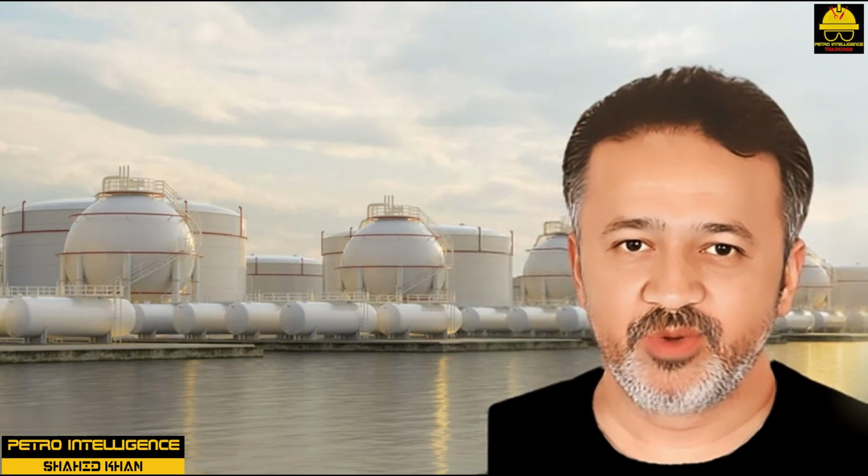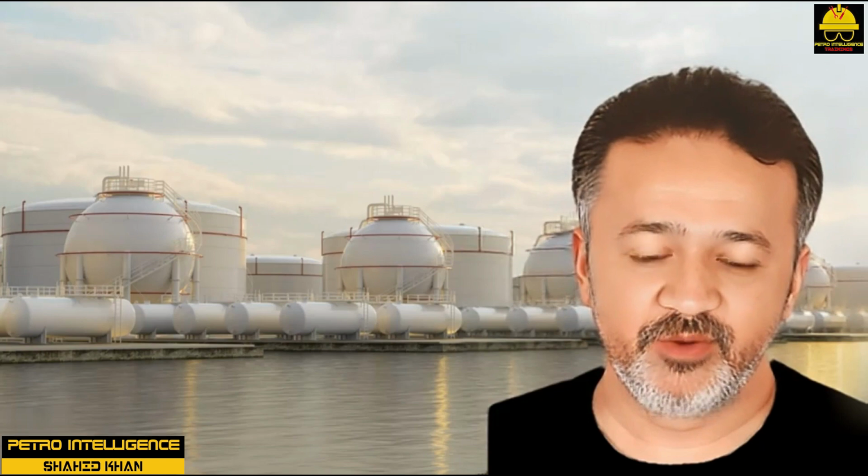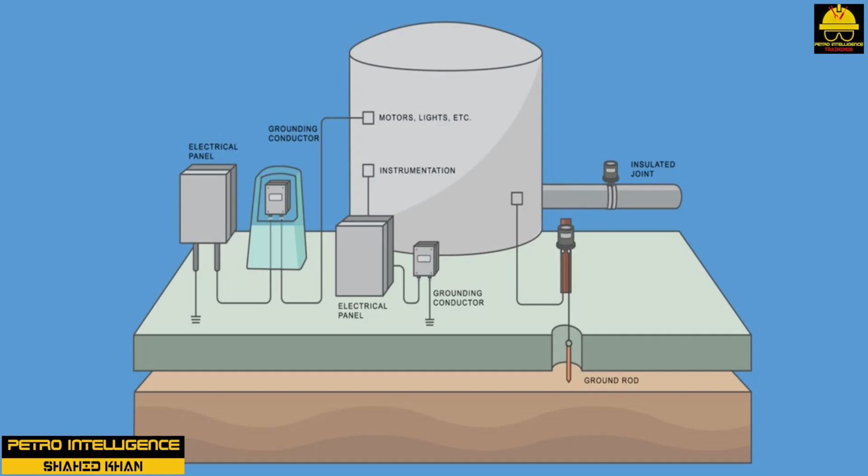The chemical industry has found two methods to prevent fire hazard from occurring: bonding and grounding. Bonding is achieved by physically connecting two objects together with a copper wire. Grounding is a procedure designed to connect an object to the earth with a copper wire and a grounding rod or grounding device. Underground water pipes can also function as a grounding device.